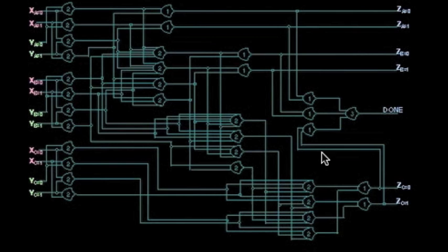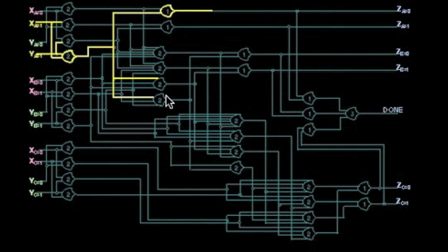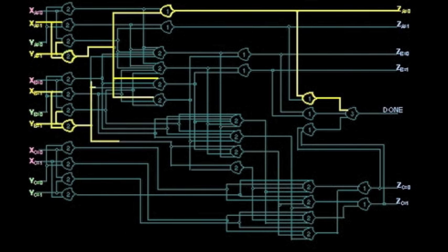It starts in an all-null state, and we begin by presenting data, which is going to propagate through the circuit as yellow. And as the data propagates, it goes to gates, and they meet thresholds, and it propagates on and so forth. And we're going to watch this gate in particular. It's a threshold 2 gate. One of its inputs is transition to data, and it hasn't met its threshold yet, so its output is still null. So more inputs are going to arrive.